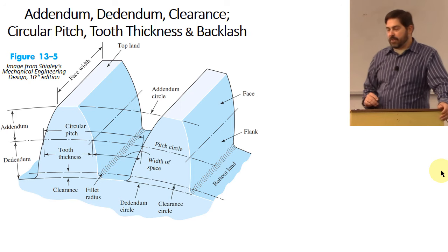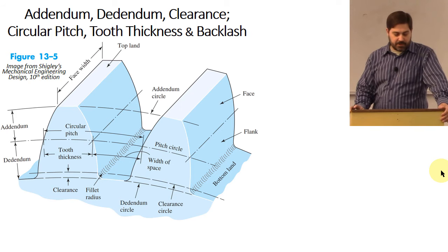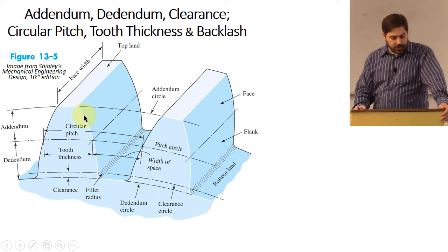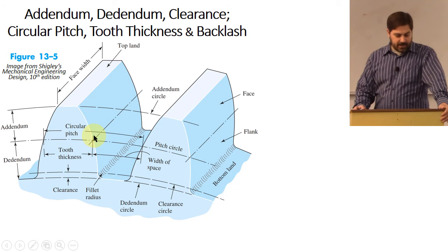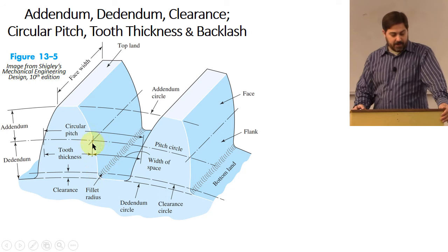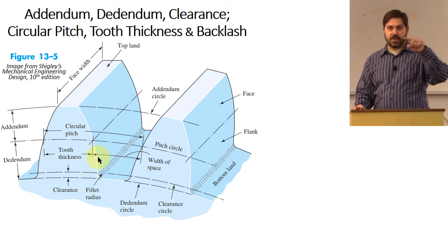There's a few other things that I think are important for you to be familiar with respect to how gears mate with each other. One of those is that the involute curve that you actually use to generate these teeth, even though it may look like that involute curve would go all the way until it gets somewhere down here in the base, that is not actually how that involute curve happens. The furthest down it can go is down to the base circle, because that's where it began to be generated.